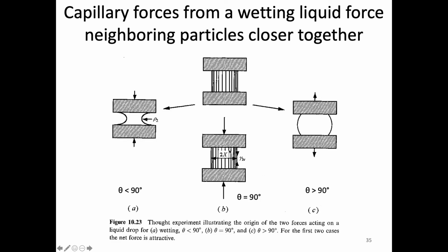And so this is not what we want to occur if we want the particles to rearrange, because in those cases we'd want them to move in some way, right? All right. So let's then look at the other scenario where our contact angle is very high, right? I already said that this is not the case that we have for liquid phase sintering. So our contact angle is really high.